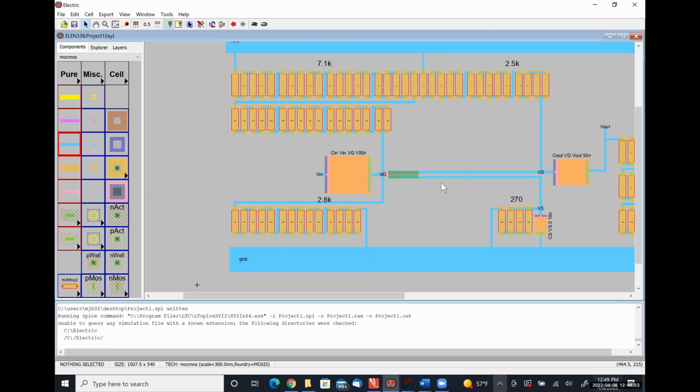So all it means when you export these things is that that's something that you can look at in LTSpice. Because I'm defining this capacitor to be placed between node VD and node Vout, if I don't export them here, it doesn't know where to put the capacitor. Or it doesn't know to interpret this thing as a capacitor between these nodes having this particular value, I guess would be a better way to put it.